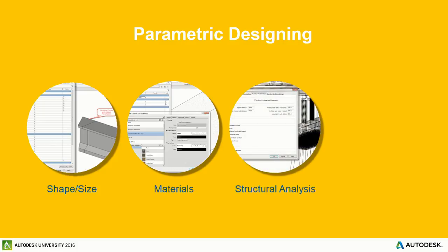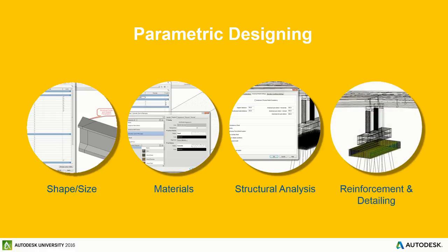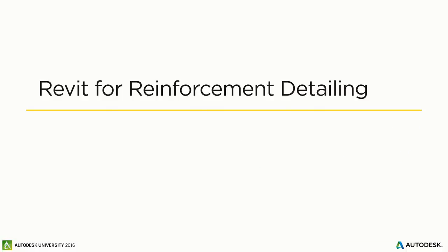Structural analysis. For those who are looking at the bridge design from that context, I know it's still early, it's schematic design. The question really becomes, does that information come across and show analytical data? If not, do we put in analytical data? And I'll show you what we get when we're in Revit. And then lastly, for those who want to get into the reinforcement aspect of the bridge design, do we want to put rebar into the initial schematic design? And so the second to last part of the workflow will be looking at reinforcement itself within Revit.